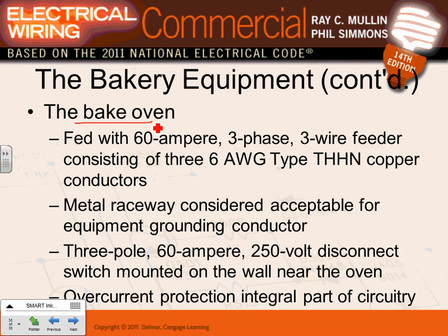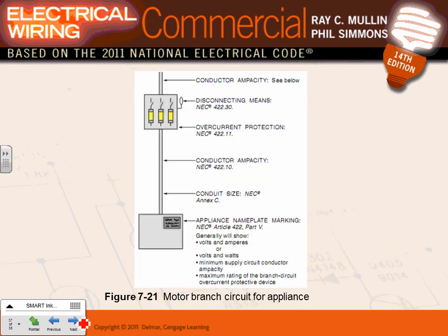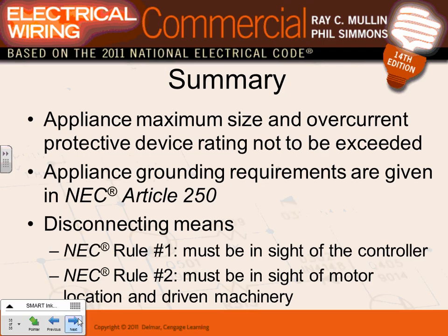We have an oven, 60 amp. They size the calculation based on the information provided by the manufacturer. You guys have done this with me. You are doing it right now with all the mechanical equipment list that I gave you, that you're sizing the branch circuits for it. So that's what I will talk about in a second.